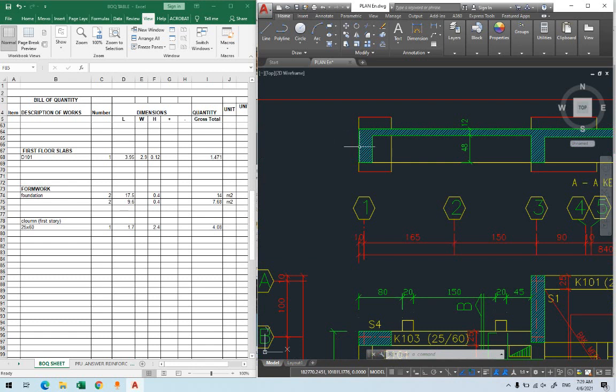Now sometimes the beams here, the slab continues. So you have to know exactly if the slab is continuous or not. Why? Because if the slab continues, the outside of the beam with the inside will be similar. For example, if the slab is continuous, it will be something like this. Those two sides will be equal height. If not, the outer side will be more than the inside. The height of the outside of the beam will be more than the inside of the beam.